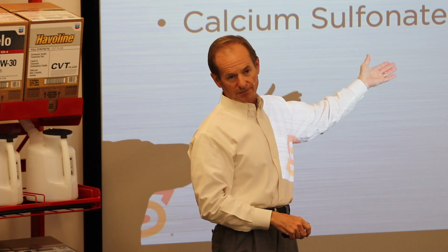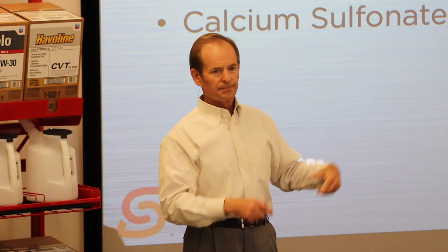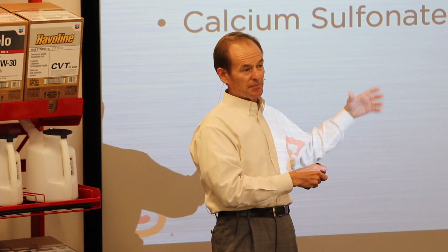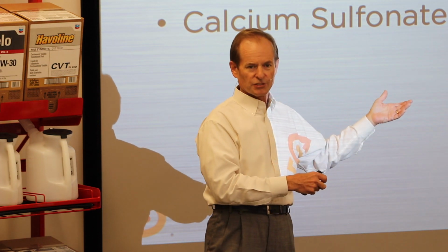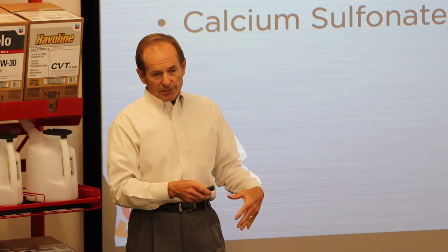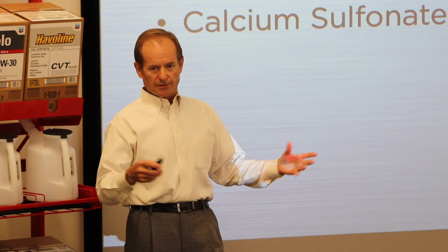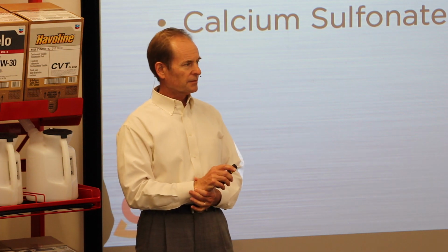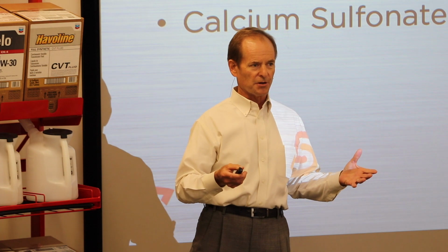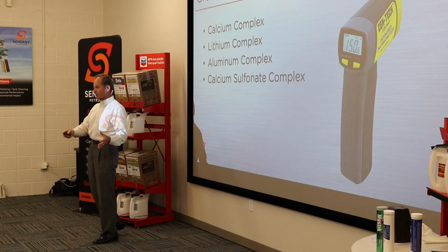That same sulfur in the sulfonate works as a built-in EP additive. You don't even have to add EP additive. You add some EP additive and your EP data go off the charts. So it's a great EP grease. Plus it's compatible with a lot of greases, so it's got good compatibility. So calcium sulfonate complex does not have a huge chunk of the market now, but it's coming down the road.